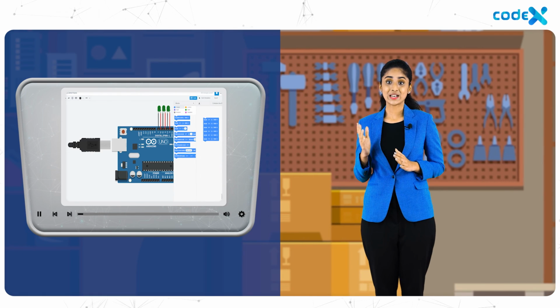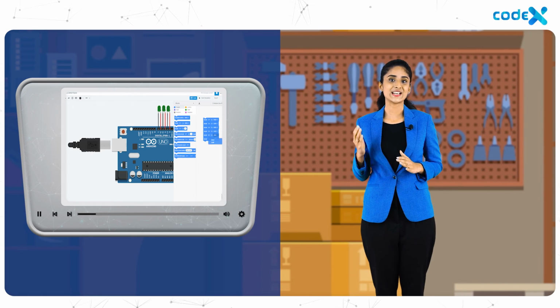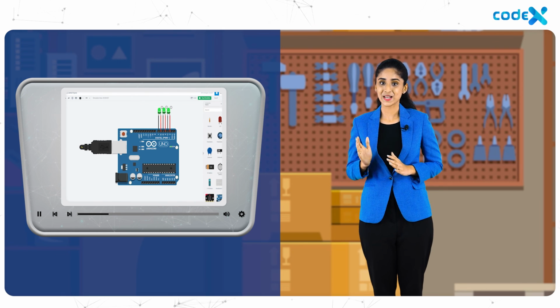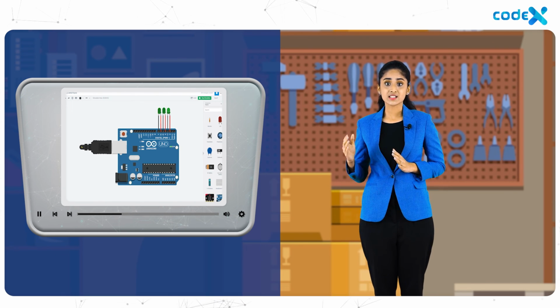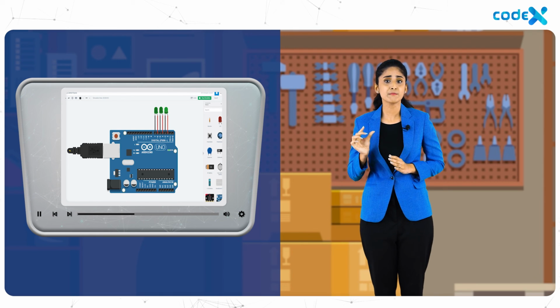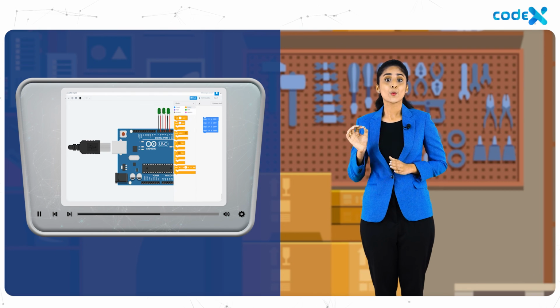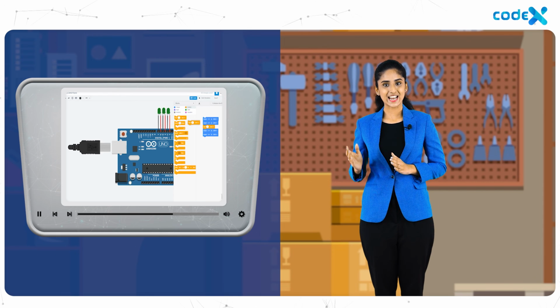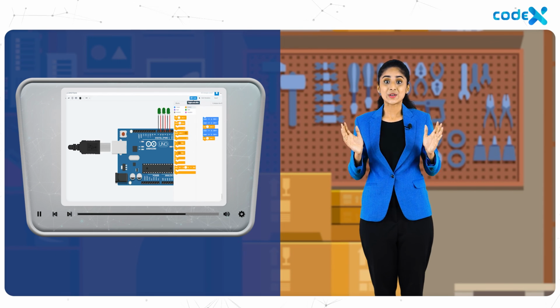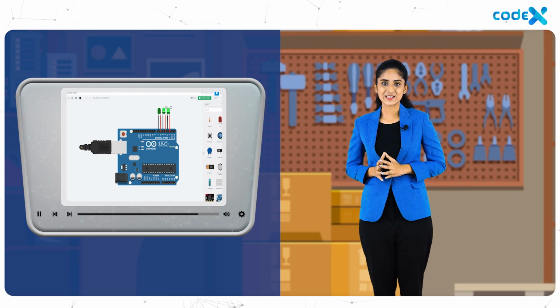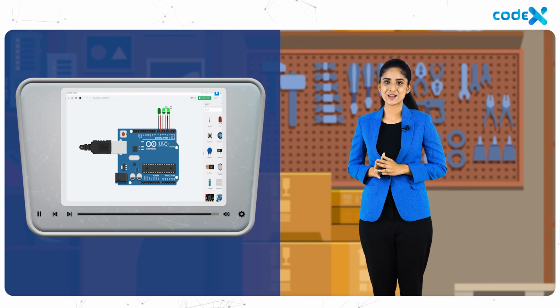In today's session, we learned about the different conditions to turn the LED off so that we could make them blink. We saw that the LED turns on and off in a fraction of milliseconds, which the human eye is not able to capture. So we introduced wait 1 sec block to give enough time for the LEDs to turn on and off. We then also created beautiful color patterns for 3 LEDs just like in serial bulbs. But there is a limitation in the number of LEDs that can be connected to the Arduino. So in the next session, let's overcome all these difficulties.